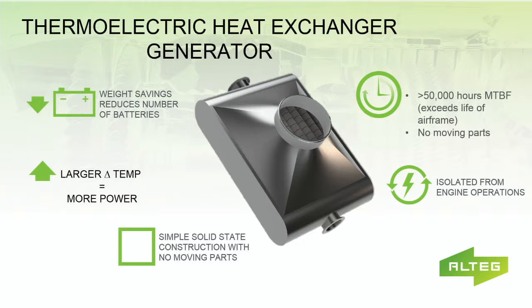What's the advantage of having a thermoelectric heat exchanger? Well, in an airplane, it can reduce the size or the number of batteries. Some airplanes have 1 battery, some airplanes have 2 or 3. Why does that matter? Well, a battery's dead weight when you're not using it. During start you use it, in an emergency you use it. Every other time it's really not doing you any good. It's just extra weight. We've got an opportunity for a huge temperature delta.